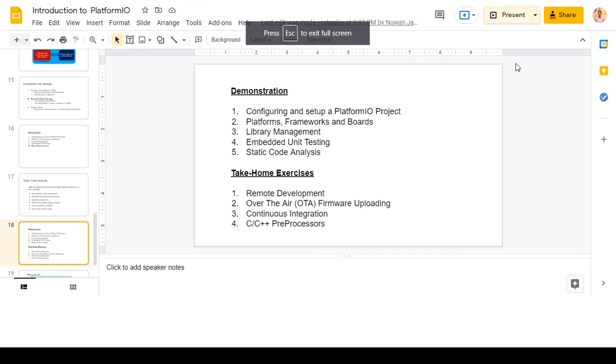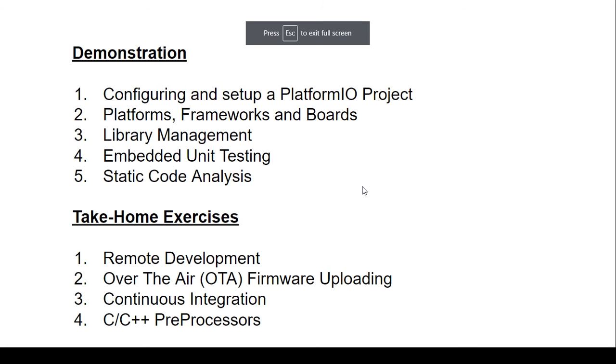So this is also a very useful tool when you are working in a group project. And the last one is actually not a tool provided by PlatformIO, but a feature available in C and C++ about preprocessors. With preprocessors, you can easily control your program. Say you write a program generally targeting both Arduino and ESP family microcontrollers, and their pin arrangements are different. Then we can write C preprocessor statements to decide at the compile stage what pin arrangement should be used for the firmware.